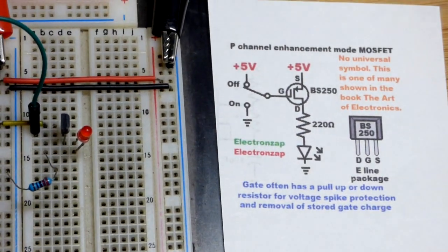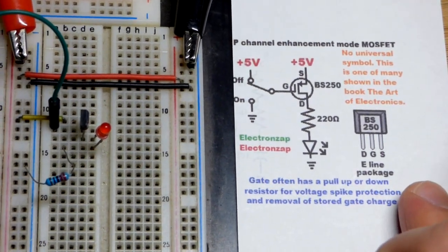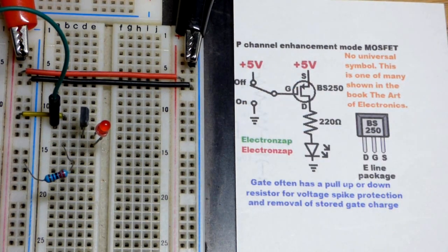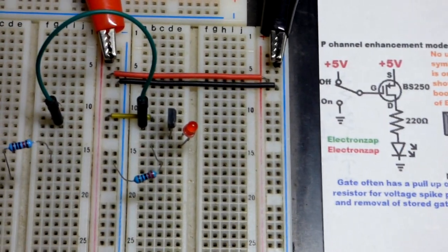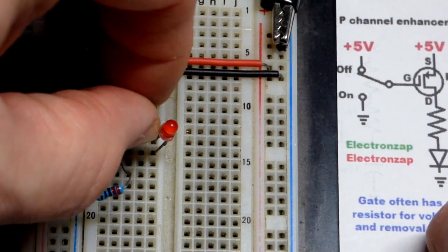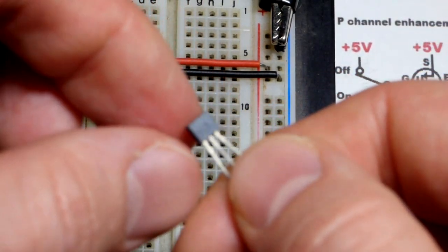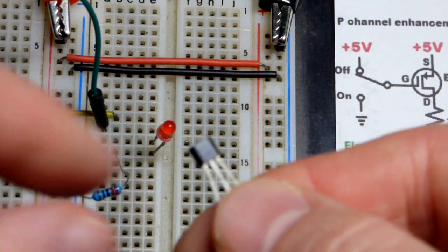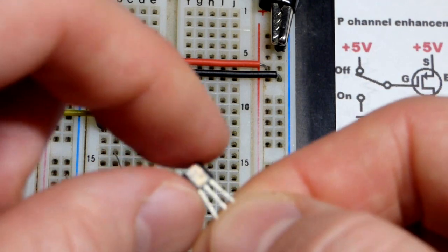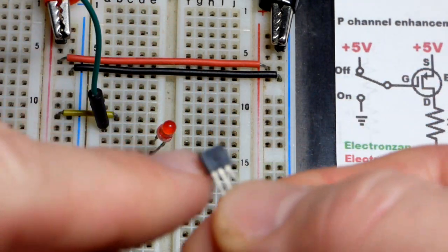Yeah, this E-line package, BS250 right there, I got from DigiKey. So I did not find one I wanted to buy on Amazon at the time. I think there are more options now. And maybe you can even get a TO92 package. But as I said before, the E-line package isn't all that much different than the regular transistor, other than the smaller side right there is the flat. And so that's the front, I mean. And the back is also flat right there.